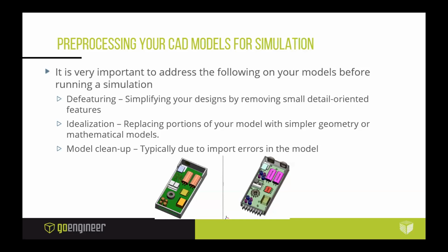Also, becoming somewhat of a surfacing guru is a good tip in general, even though we're simulation people here or interested in simulation. Being able to use the surfacing tools to resurface or delete face and patch, all of these features are going to be really helpful to fix imported geometry. So model cleanup is going to be huge when you're doing simulation, potentially if you're importing. Also, when you're importing, it's a good idea to import with Parasolid as a dummy body. That's the modeling kernel we use in SolidWorks. So import as a Parasolid whenever possible. Any questions on this?